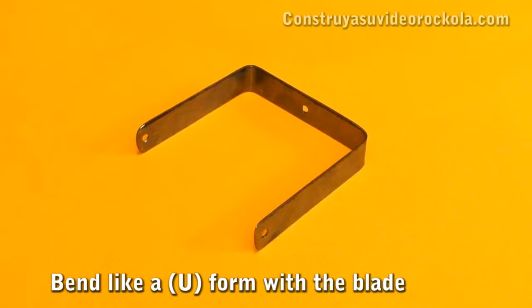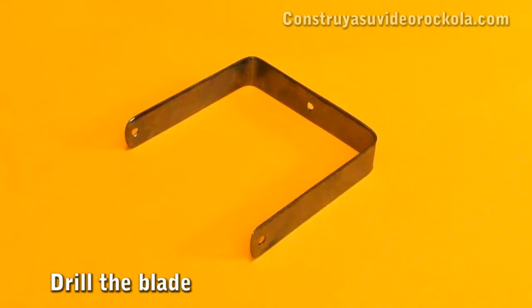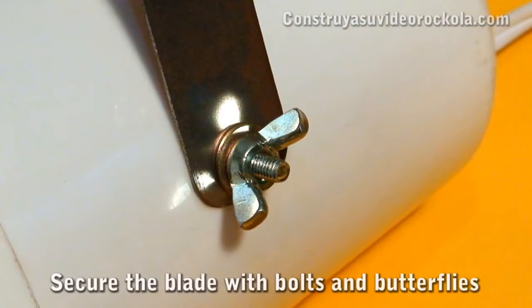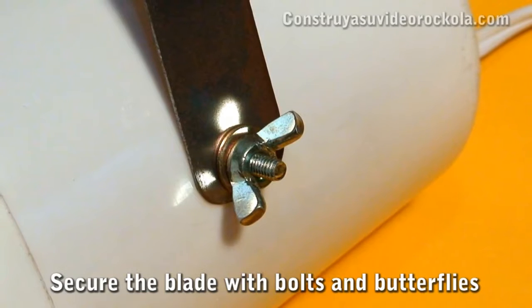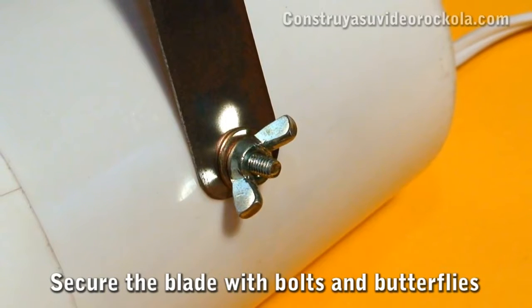The metal sheet will serve as a strobe support. Bend it into a U. At each end, make a hole using a drill bit of the same diameter as the screw that fastens the sheet to the jar. We make a couple of holes on the sides of the bowl and put in the screws, holding them with washers, leaving the wing nuts on the outside so you can adjust to your preference and change the angle of the strobe.